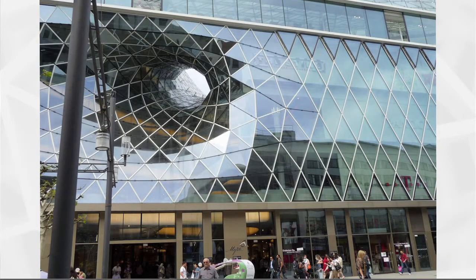And so I love this slide. This is a Massimiliano Fuksas building. And this is a gorgeous panelization where they strove to create everything very, very regular. You have some very regular connections over here. As you merge into this concave shape, you have the regular connection of a triangular grid. You have one vertex and 6 connections. But remember, the Euler characteristic is fighting to be shown here. So what happens? Well, you have one giant connection here, where you have 1, 2, 3, 4, 5, 6, 7 connections.